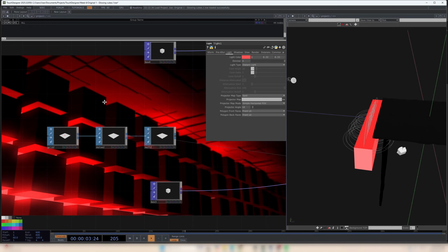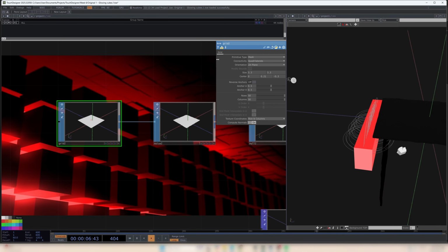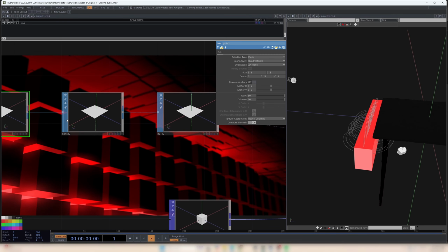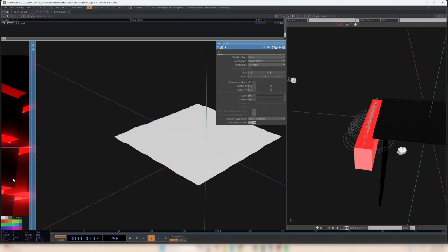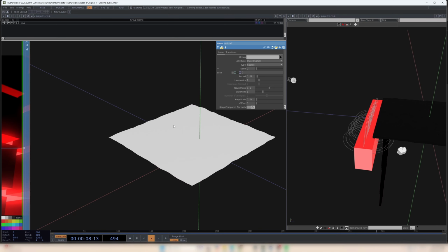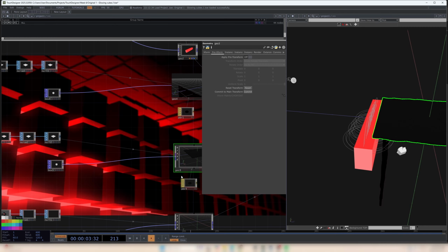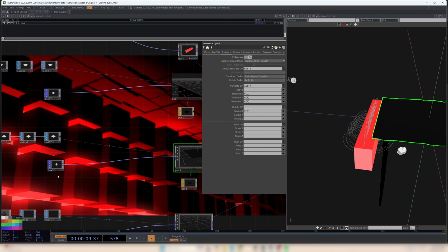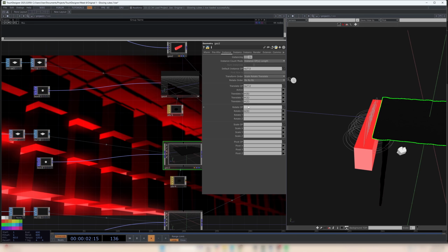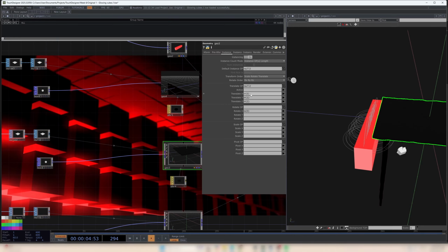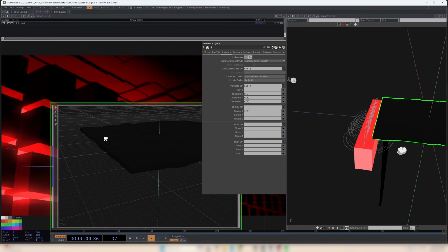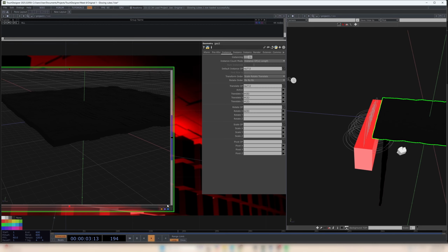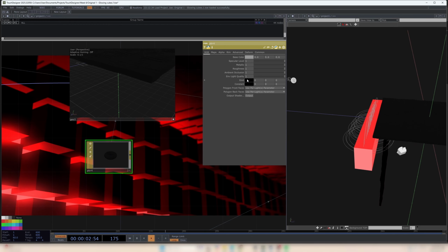At the core of this project is a grid. This is actually a SOP grid, which we then feed through a noise, and you can see here I've set this noise to very low amplitude and period as well, and we just get this slight rippling. Then we feed it into a null and we instance in the geo here. In this instance I've instanced null2, connected this box to the geo, and now we translate across the P0, 1 and 2.